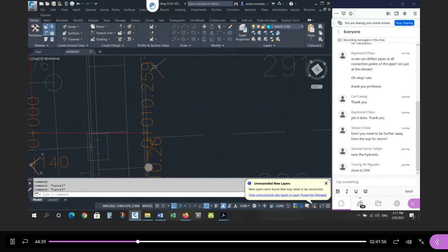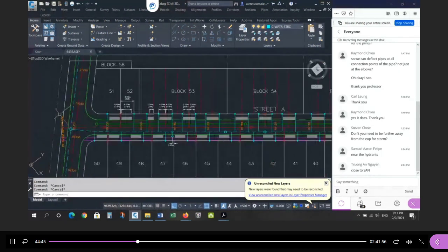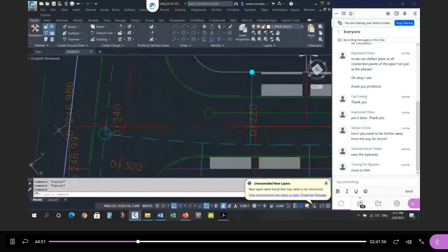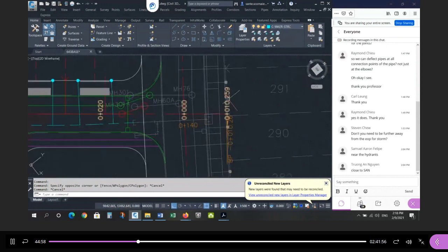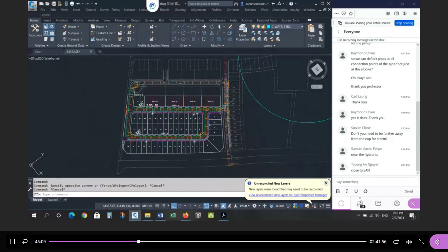That's the beginning. 0 is at the intersection, and positive chainage takes you all the way to the street line, the edge of the subdivision, right? Not the intersection, all the way to the edge of the street line. The station at the end should be 246.986. So if this number's not there, I took a mark off. If this number's wrong, I took a mark off. Okay, so you had to have the extent. The geometry needed to be correct, and the definition of the alignment needed to be correct. Positive chainage increasing in this direction, 0 in the right spot. Positive chainage in this direction, 0 in the right spot. Okay, so that's what I look for. And you'll see a breakdown.